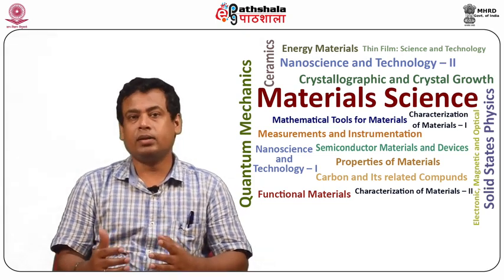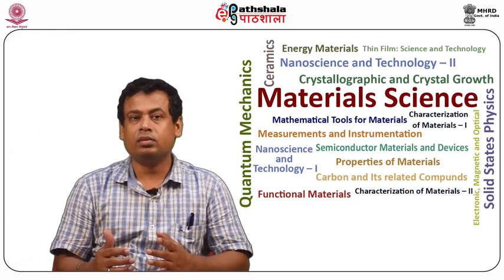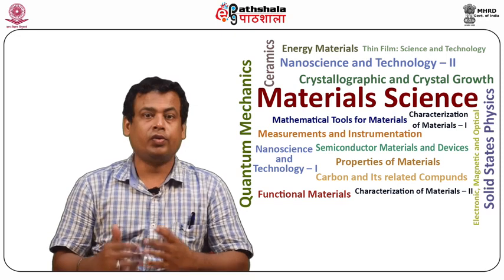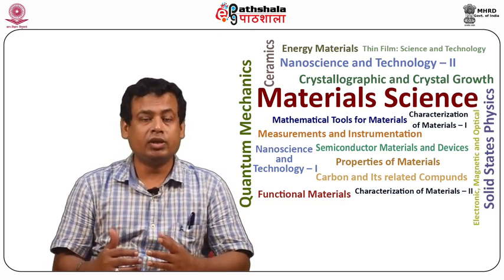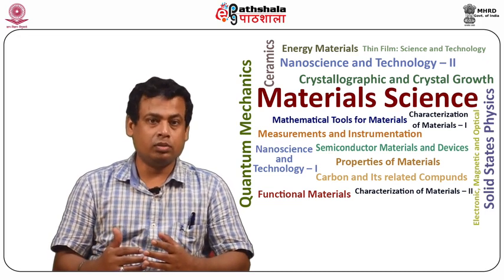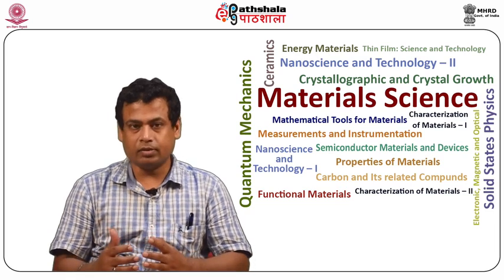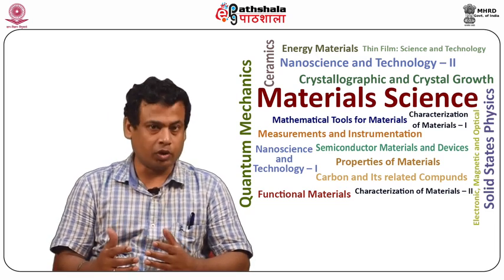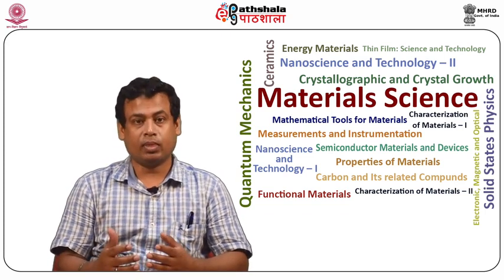Alignment is made for each stage position, either by checking for registration masks or using a laser interferometer to precisely measure the stage movement. A good quality substrate for electron beam lithography must satisfy various conditions stated below.